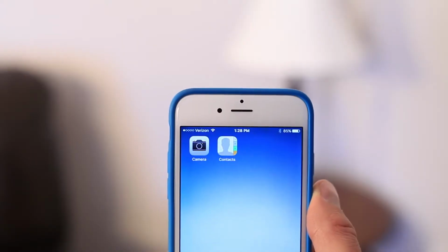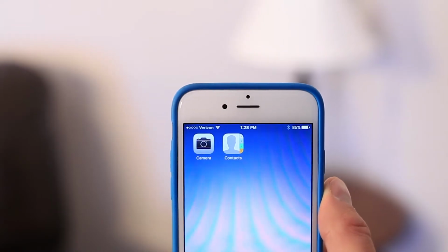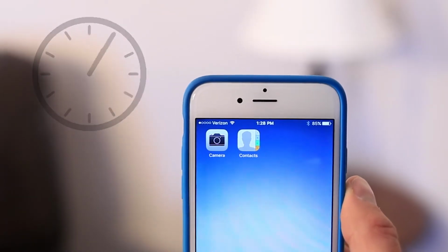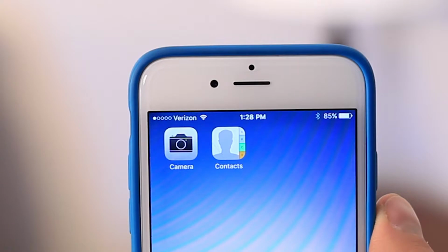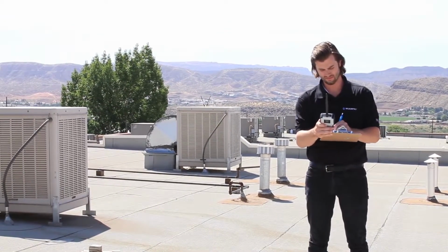Using your phone to test signal strength is less effective and reliable. Your phone takes a while to update the signal, sometimes up to a minute. Also, since your phone is tied to a carrier, it will only read the signal for that specific carrier and band it uses. There's no way on a phone to read all 5 frequency spectrums.